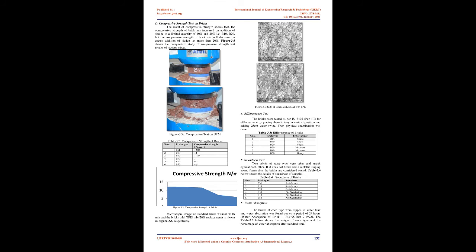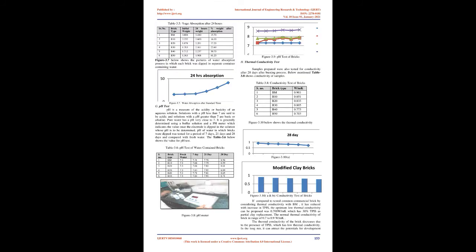Hardness test. This test was done to know the hardness of bricks. In this test, scratches are made on the surface of the brick with a hard object. If it does not leave any impression on the brick surface, then it is considered a good quality brick. Further, in the structure test, a brick is fractured and closely investigated. If any flaws, holes or cracks are seen inside the broken brick, then it is considered a poor quality brick.